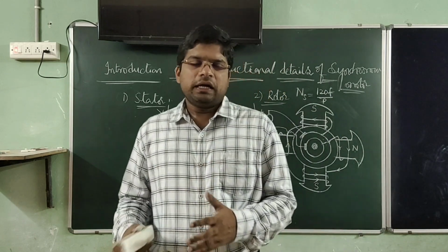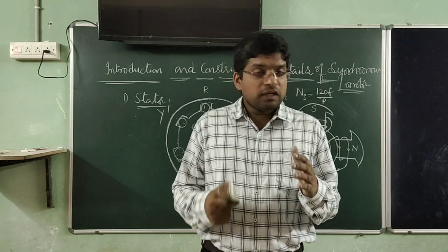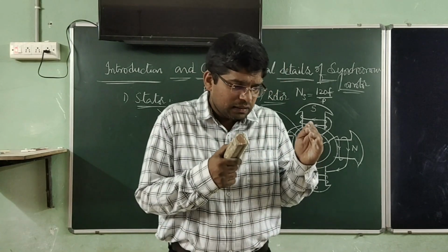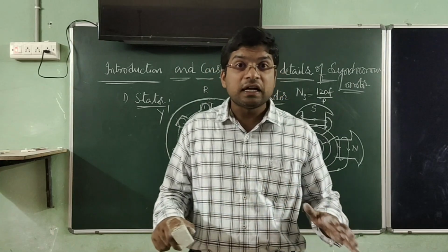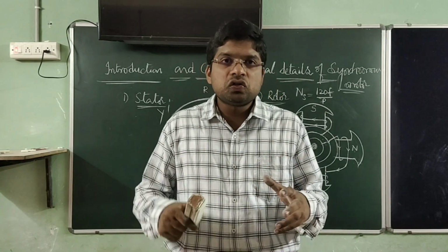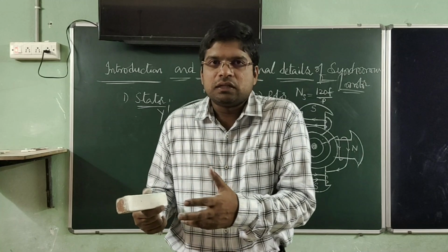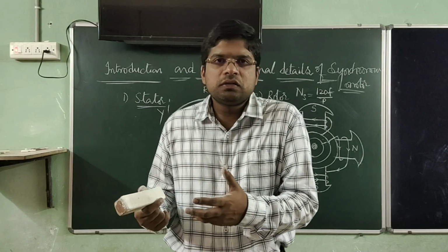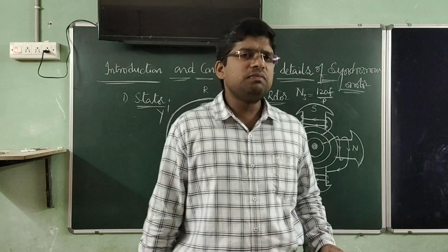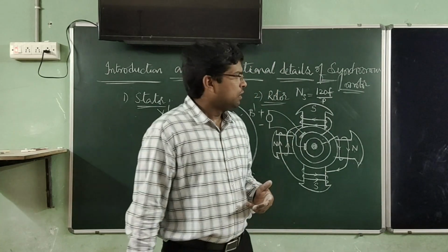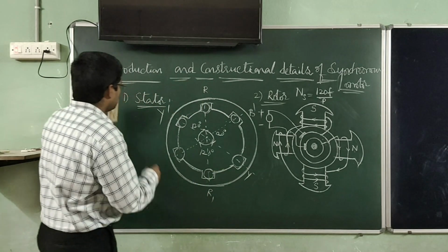The final and very important point is that synchronous motor is not a self-starting motor. It requires some external means to start it. That external means can also be called auxiliary means. This auxiliary means may be in two ways. First way is by using induction principle.